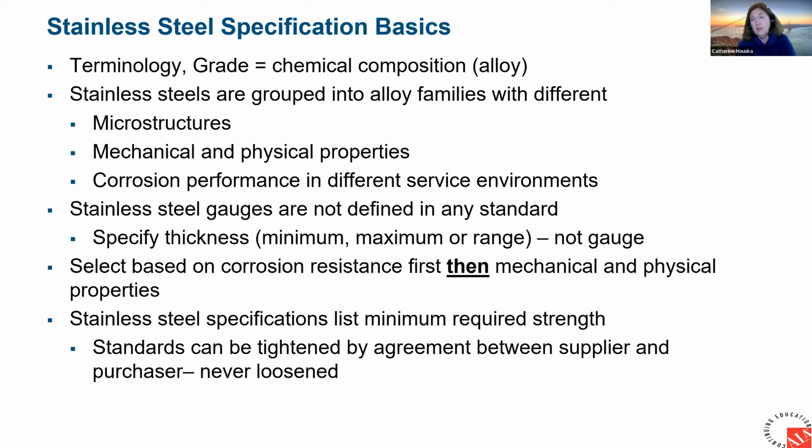There is only one stainless steel standard in ASTM that actually has strength grades. That's for laser and laser hybrid welded stainless steel structural sections. But otherwise, the term grade means alloy. So make sure that you're talking about the same thing.